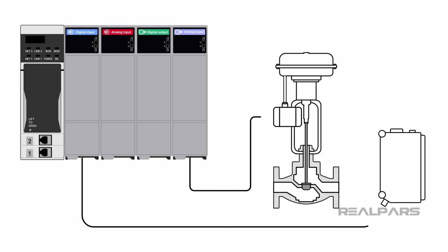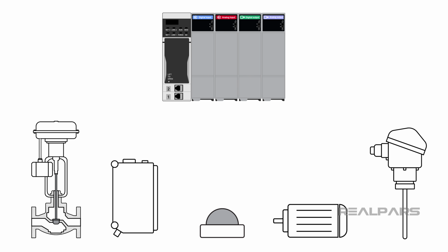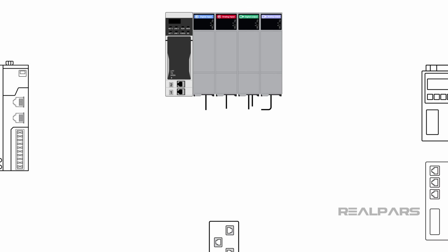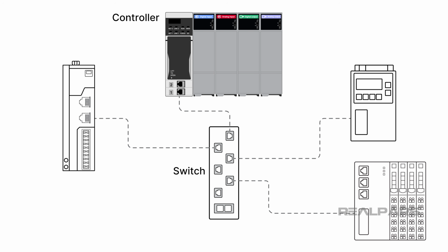At the beginning of this video, I described an IACS where the input modules are connected directly to the logic module. But in a large IACS, there can be thousands of input and output devices that are spread over a large area. In these systems, it is very difficult to wire all of the devices back to the logic module. Instead, industrial networks are used to connect the logic module to remote devices like I/O stations, VFDs, and servo drives.